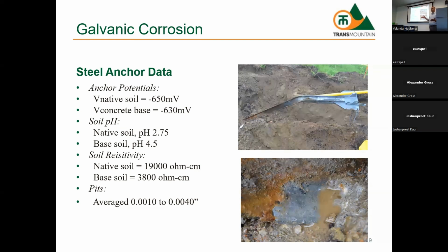Relatively they were close because they were in the same concrete block. But the steel went into the top of the concrete, and the copper came around and then back up. So the whole length of the copper was red. It looked just great. There wasn't a spot where the copper wasn't being protected cathodically due to the proximity of the two metals.